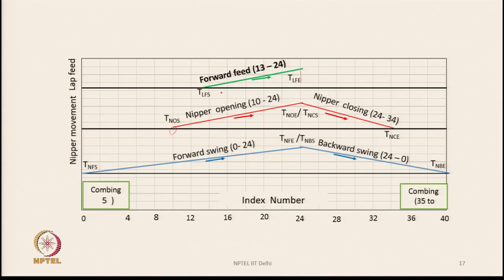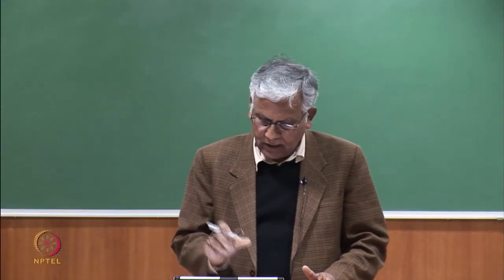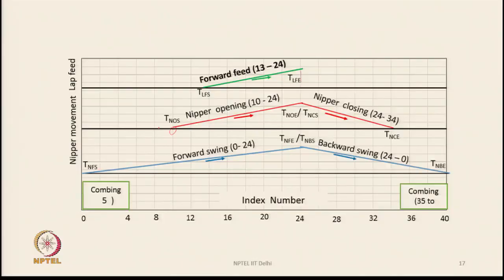We cannot start the feeding process earlier, because if we go below 10, the nippers are not open, and in that case the lap sheet is going to be piled up. So, keeping in mind all three conditions stated in the previous slide, the time available for feeding the lap sheet will be somewhere between 13 and 24.